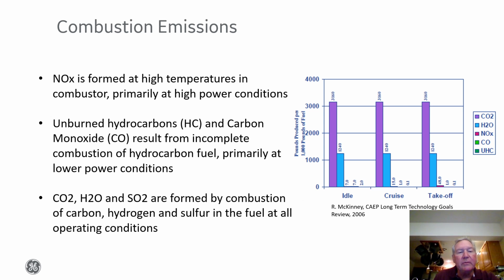So a few notes: NOx is formed at high temperatures in the combustor, primarily at high power conditions. Unburned hydrocarbons and carbon monoxide result from incomplete combustion of the hydrocarbon fuel, and these emissions are produced primarily at low power conditions. CO2 and H2O, of course, are stable products that are not harmful or regulated, and sulfur dioxide is formed by combustion of sulfur that's in the fuel.